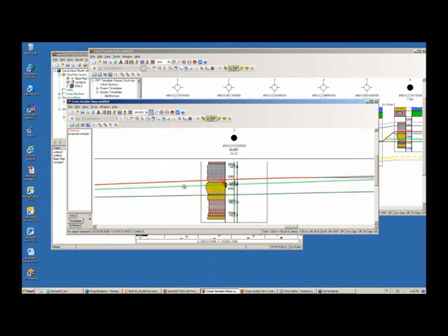What you're going to notice on a projected line of section is some little solid or hollow sideways triangles. The solid triangle means that there was a pick made on that well at the site of the well. This is the pick or formation top, which is stored in well base. This pick was either interpreted by you, the geologist, or imported from some outside source. If the pick is hollow, it means that smartSECTION estimated its position based on the nearby picks. If it's solid, it's obviously your pick.